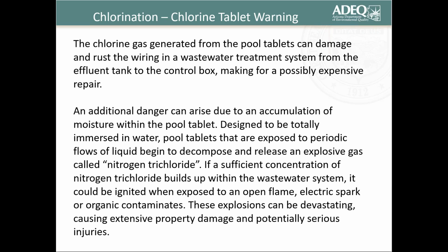Designed to be totally immersed in water, pool tablets that are exposed to periodic flows of liquid begin to decompose and release an explosive gas called nitrogen trichloride. If a sufficient concentration of nitrogen trichloride builds up within the wastewater system, it could be ignited when exposed to an open flame, electric spark, or organic contaminants. These explosions can be devastating, causing extensive property damage and potentially serious injuries. So people do not want to use pool tablets in a wastewater treatment device.